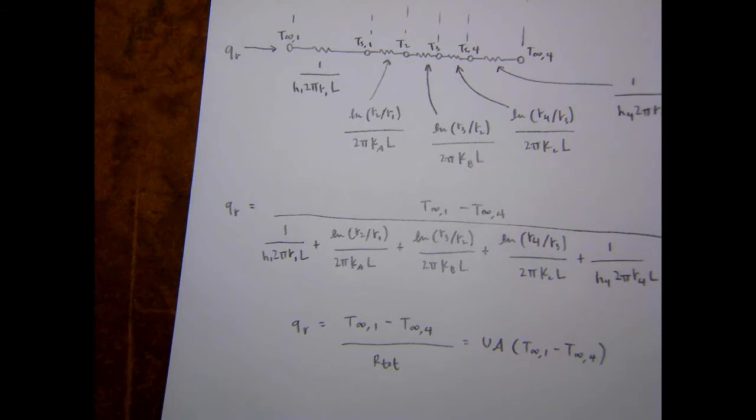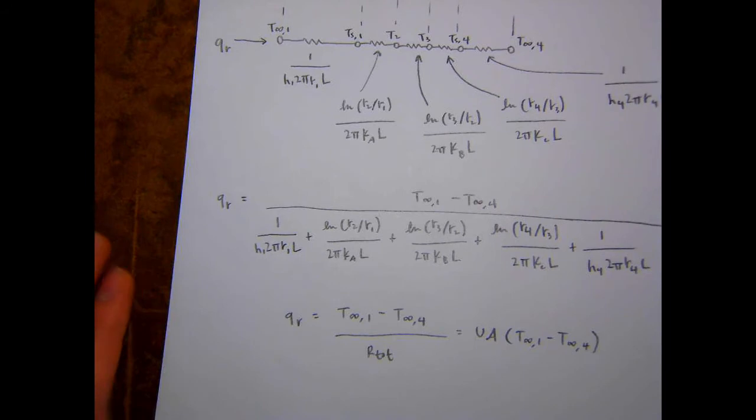And for fins, for extended surfaces, the big distinction that you need to think about, and we'll write this down in the notes too, is now you have a very thin surface and you've got conduction in one direction and convection perpendicular to it. That's a big distinction that I want you to be thinking about when you're looking at the systems that we have been looking at before, like the cylinder or plane wall, and then fins, extended surfaces. So you have to treat them a little bit differently, come up with different equations, and redo the math for those particular setups.